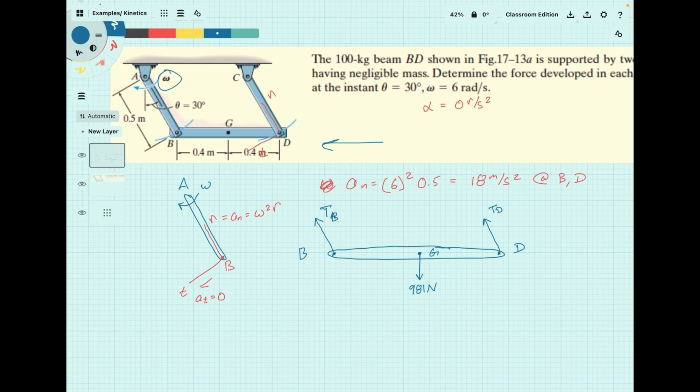Those are the only ways that it can transmit forces along the direction of acceleration. So those are your two force vectors, essentially. And so those will both be at 30 degrees off of the vertical. Now, as far as it goes, those are going to be equal in magnitude in the end, but we'll sort of prove that as we go here.